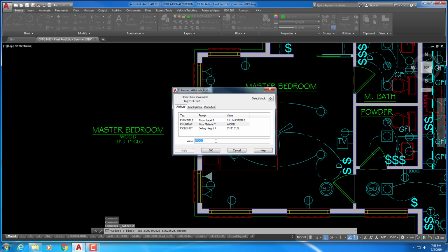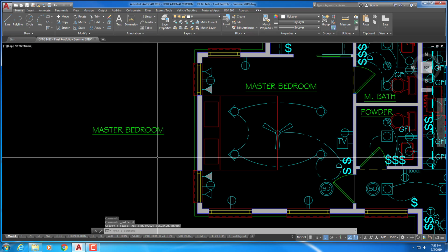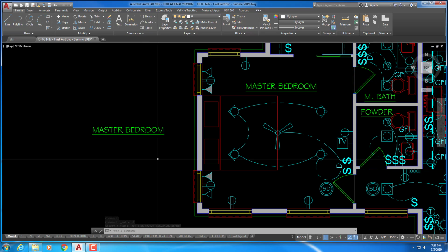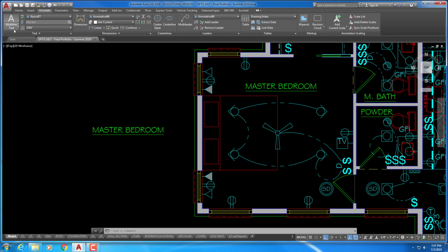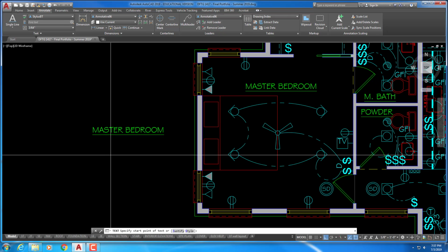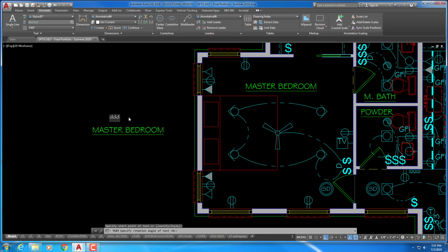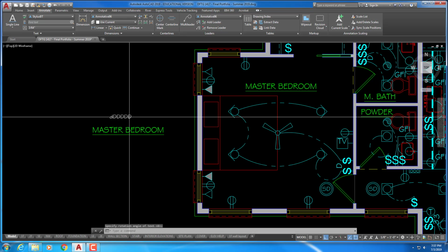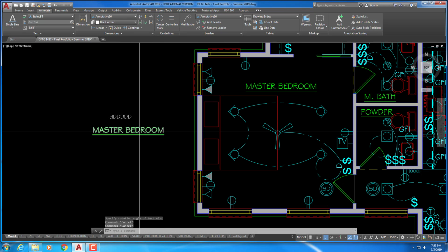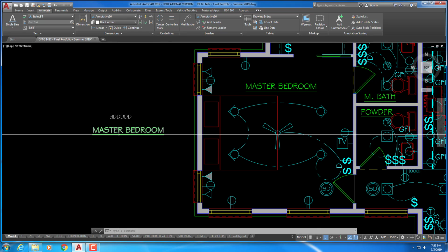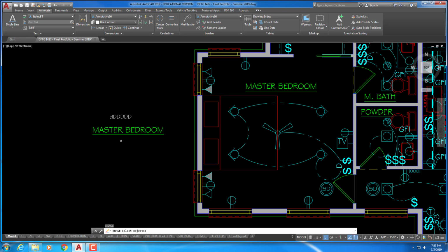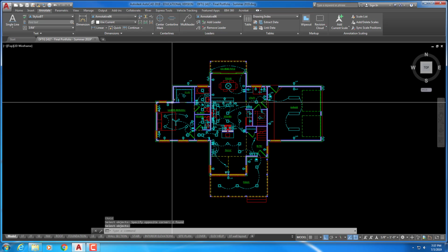So what you need to do is just edit that to where the ceiling and the floor is out, and then just copy that around and change the text. It should not be this size text. If you put in this size text, that'll be wrong. So this is wrong. It needs to be the same size as what was on the first floor that you can copy to layer. If it's a block, you won't be able to copy. As long as it's exploded, you'll be able to copy it over like I just showed you. And the same thing would apply to the second floor.